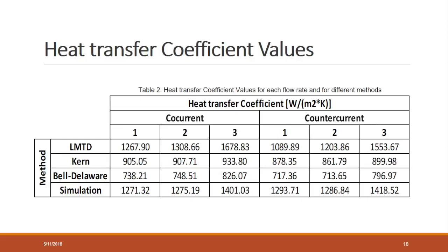The assumptions made for each method can also affect the final value of the heat transfer coefficient. For instance, the current method considers co-current flow to determine the equivalent diameter. Thus, there is an alteration in the counter-current flow calculations, which can explain why its heat transfer coefficients are lower than the co-current ones. Furthermore, the current method is a simplified method that puts aside the cross-flow and baffle window flow in the shell, generating deviations in the calculated heat transfer coefficients.